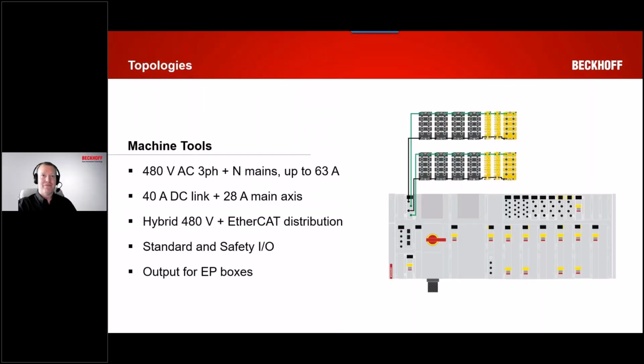You might have a light curtain out there. You might have a door switch that's on safety. We can put remote safety boxes. Whatever device, it makes more sense to put that on EtherCAT and have either a single cable on EtherCAT, or cable and power on EtherCAT and power coming back. That is the point, right? We're wanting to move to that distributed side of things.